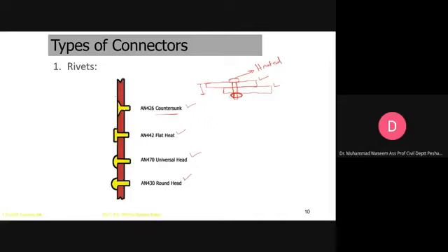When it starts cooling, it will shrink, and when it shrinks, it will apply clamping force on these surfaces. These clamping forces are responsible for holding these two plates together.